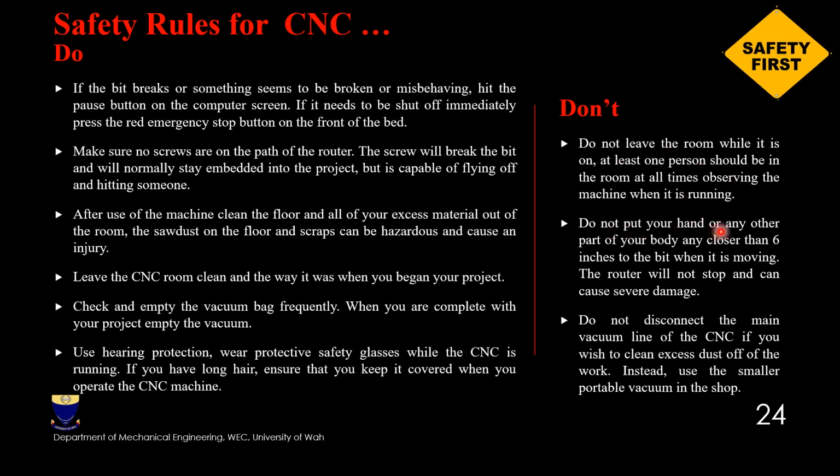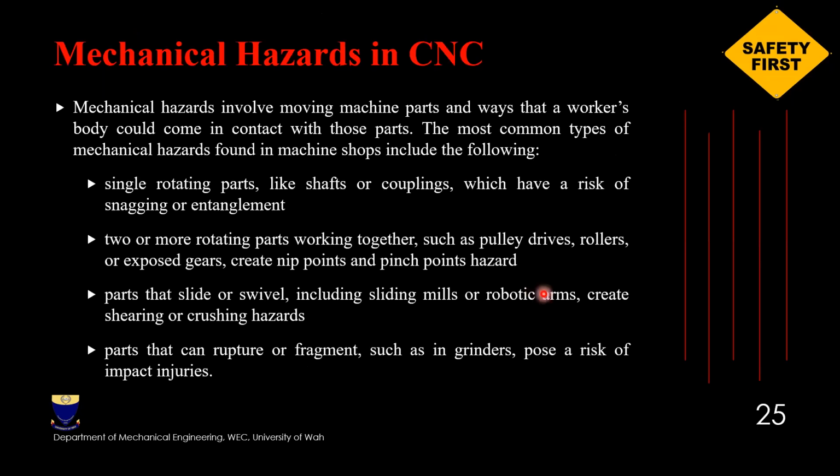Do not put your hand or any other part of your body any closer than 6 inches to the bit when it is moving. The rotor will not stop and can cause severe damage to you and in some cases to the machine as well. Do not disconnect the main vacuum line of the CNC if you wish to clean excess dust off the work. Instead, use smaller portable vacuums in the shop for cleaning chips and dust over the CNC vacuum as well.